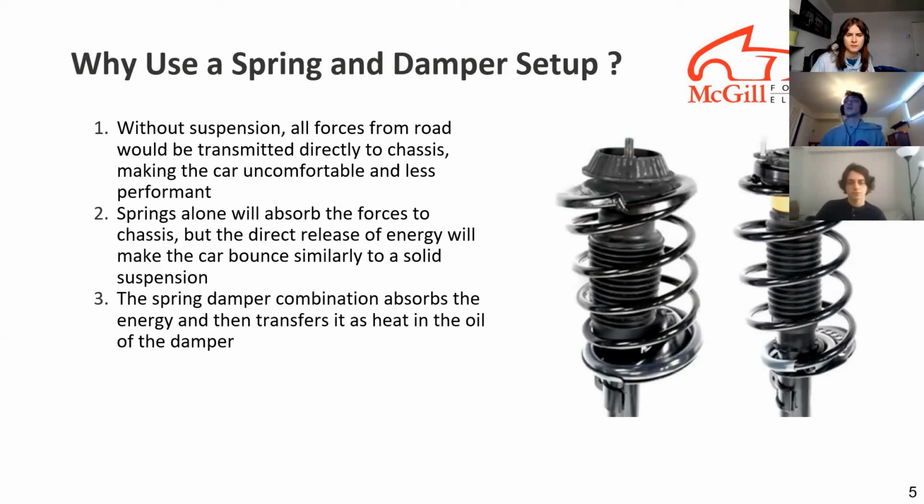And then if we use only a spring setup, it will absorb the energy from the road. However, it will also immediately release that energy back. So you'll see the car bounce around. That's where the solution of the damper and spring setup came about. The damper is used to reduce or absorb the energy from the spring and transfer it as heat instead of kinetic energy.